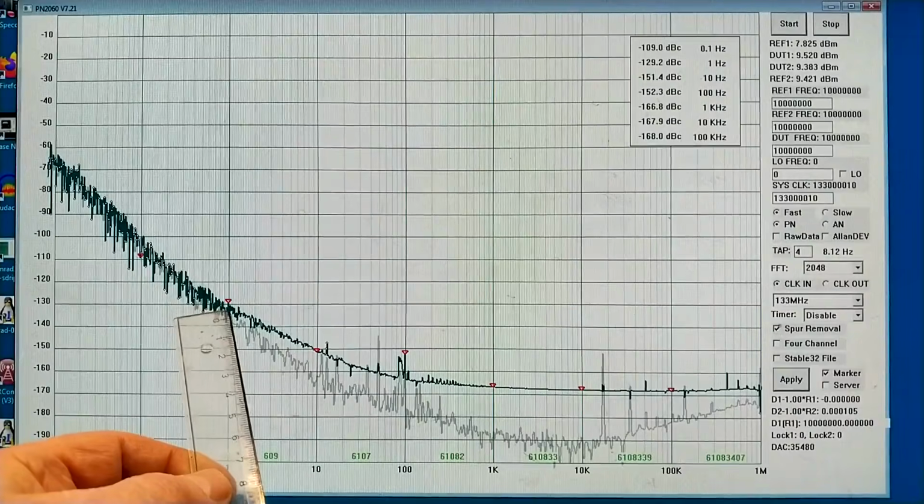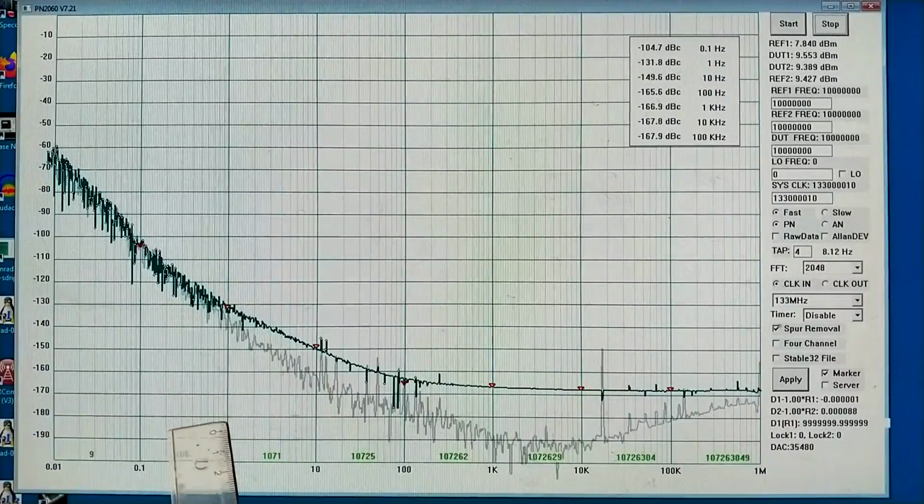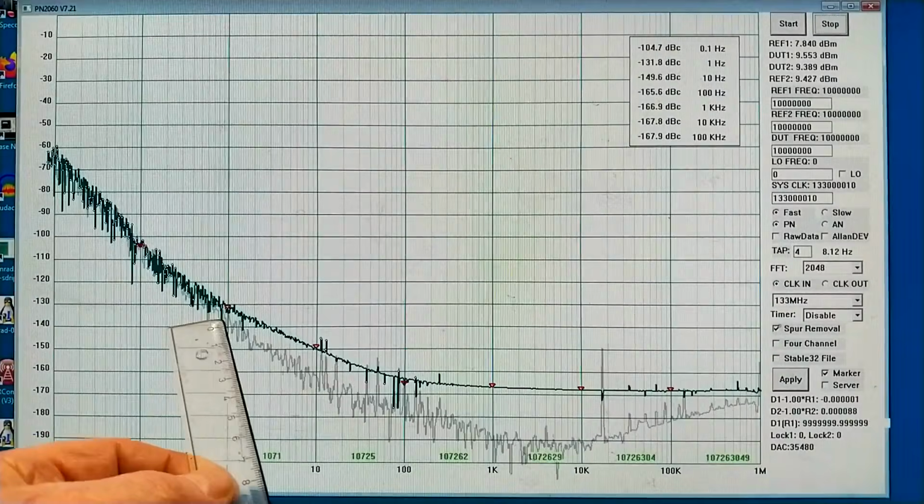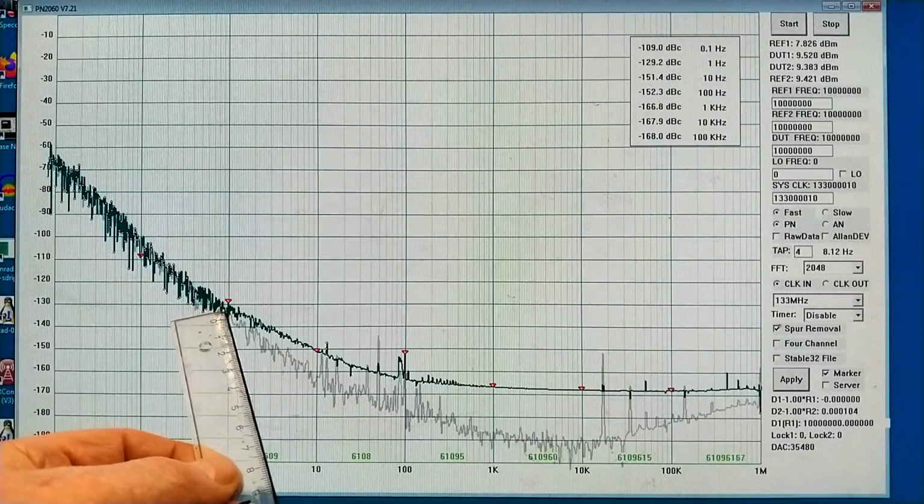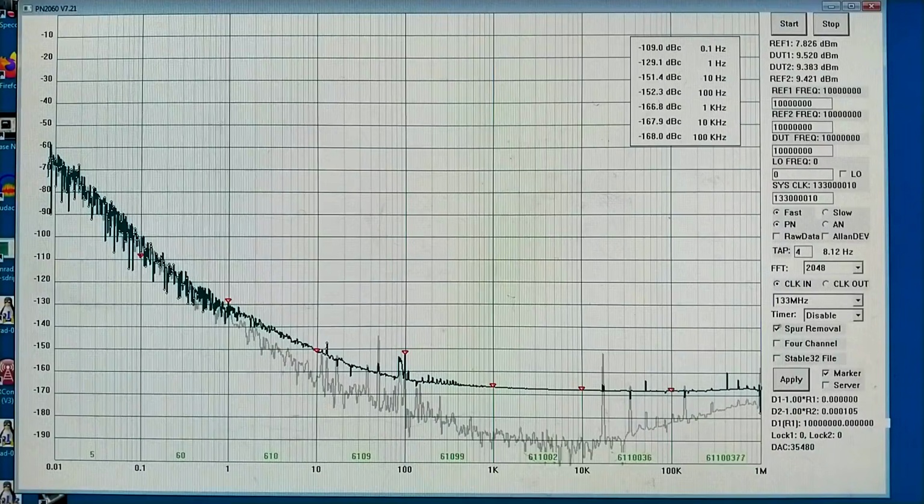Here statistics is not good enough. But still one can see that it's about 1 dB or perhaps 1.5. So it is not a big difference. But one of the things that has happened is that the output impedance has become larger, which means that the signal level has dropped by about 1 decibel.